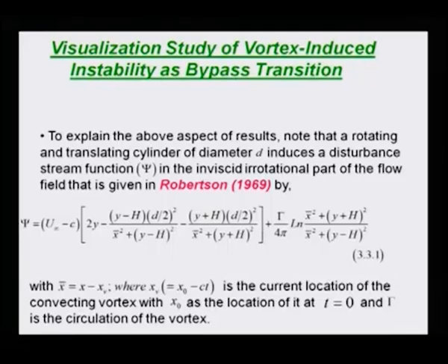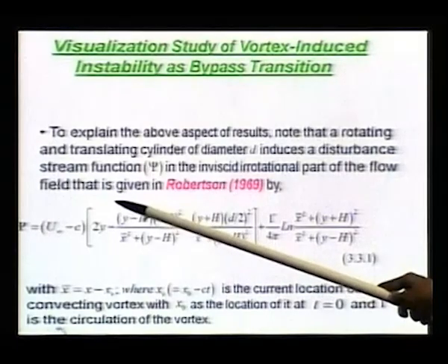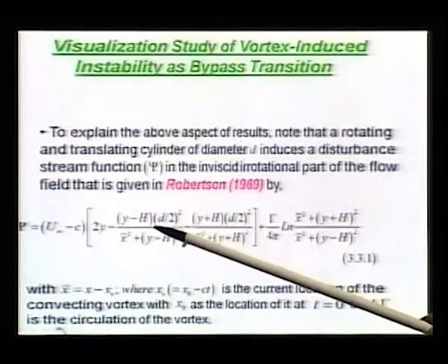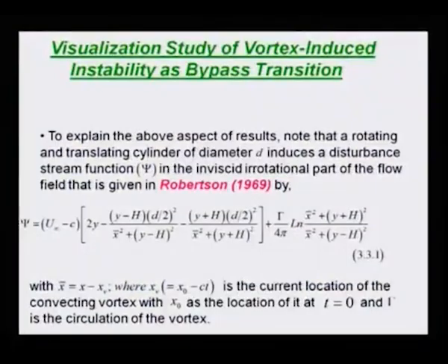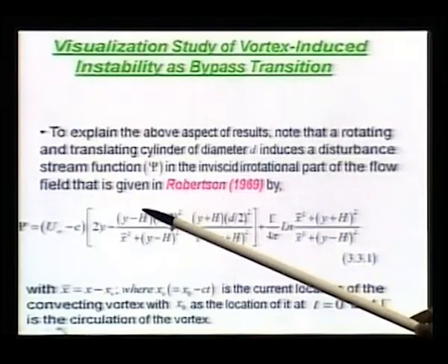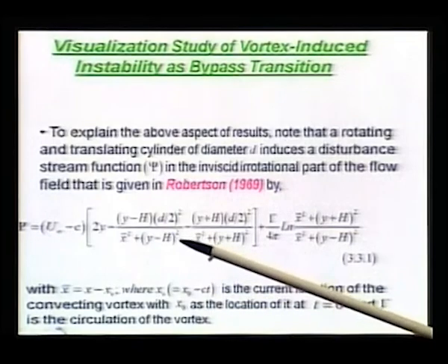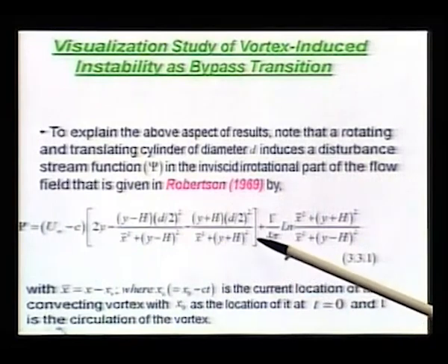So, the relative speed is U infinity minus c, and this 2 y corresponds to the uniform flow part, and these correspond to a doublet and its reflection, because it is going in front of a flat surface. So, you get a reflection at the same height. In one case it is plus h, in another case it is minus h.